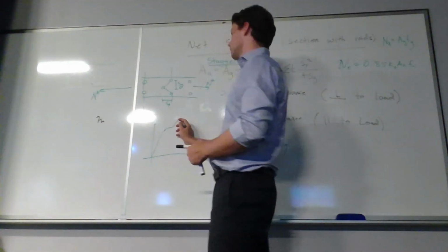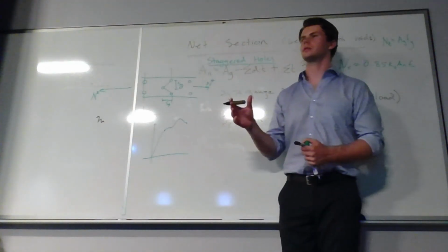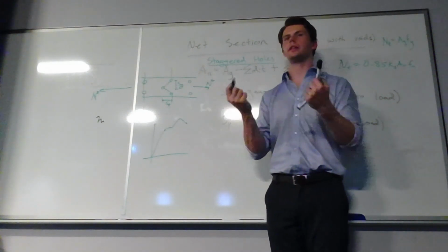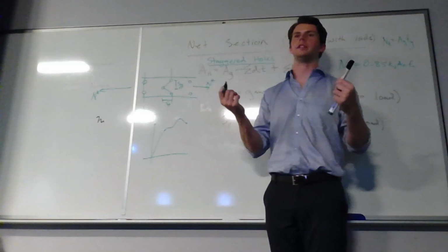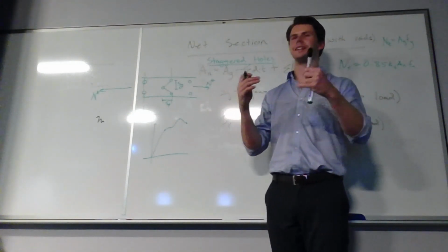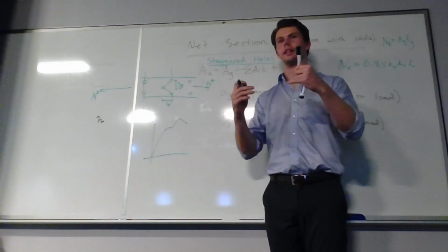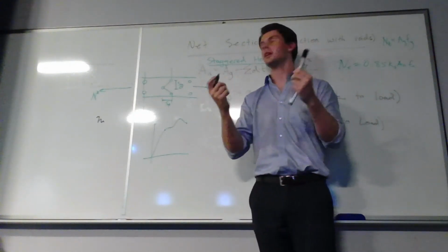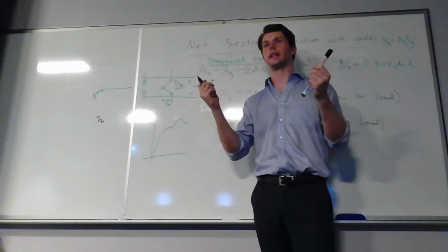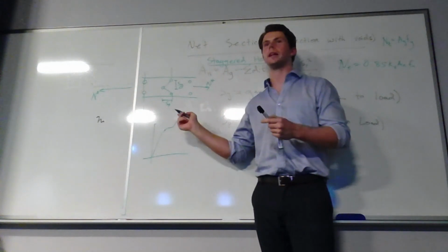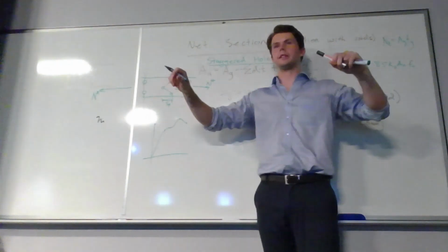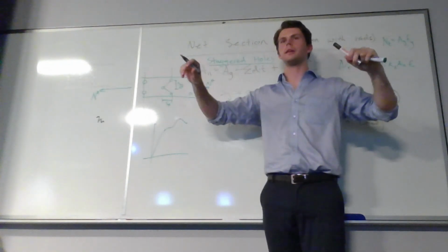That's work hardening, right? I think that's when you keep on straining the steel or whatever material, and then it actually gets stronger because of the crosses between the dislocations. So if you stretch a material past its yield point, sometimes that material can actually get stronger, even though it's gone through plastic deformation. Say you stretch steel, it won't go back to its original shape, but it might actually be stronger after you've stretched it a little bit.